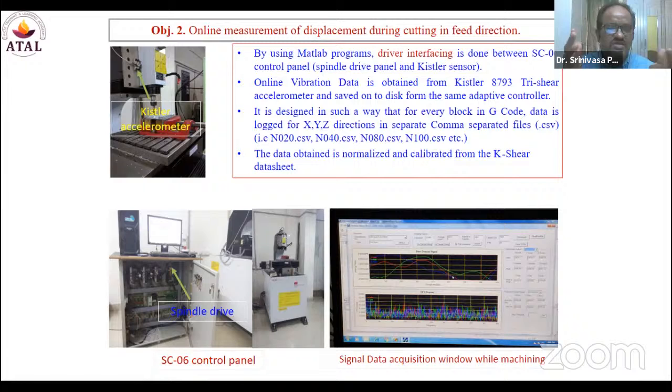So you need to look into whether any of the objects under your investigation is in rotating condition or not. If any object under investigation is in rotating condition, you can blindly follow the instructions of ISO 10816.